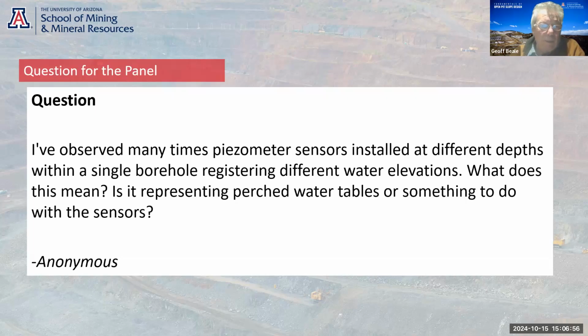So this is an absolutely normal situation. And in fact, if you didn't get a vertical gradient, you'd be wondering why not. You'd be questioning the sensors. It'd be strange to have the same pressures or the same water level, well, it wouldn't be phreatic level, piezometric level, in all the sensors. You'd probably question whether the sensors are grouted in properly.